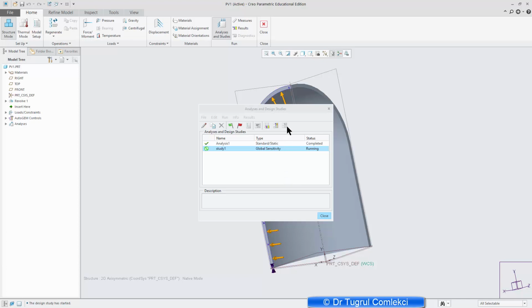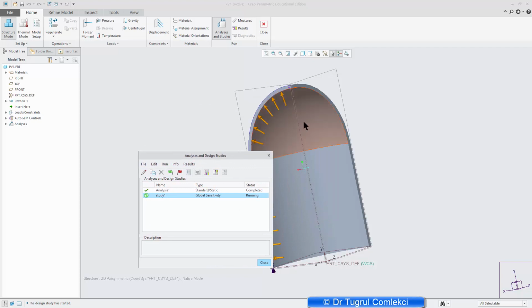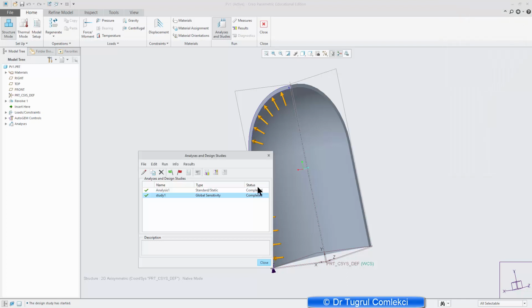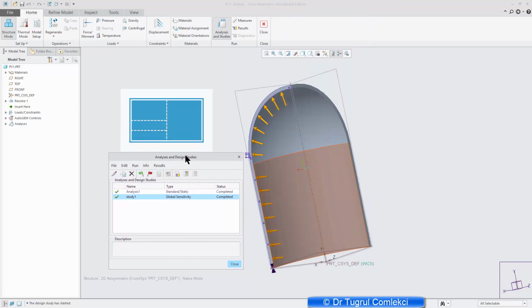But what you might find is that if you are looking at a large 3D model with many solid elements, for example, and complex stress variations in the model, which requires high p orders, you might find that this will take significant amounts of time, especially if you're asking for too many steps. So initially start with a low number of steps, make sure your analysis works okay, and then look at increasing the refinement of your model.